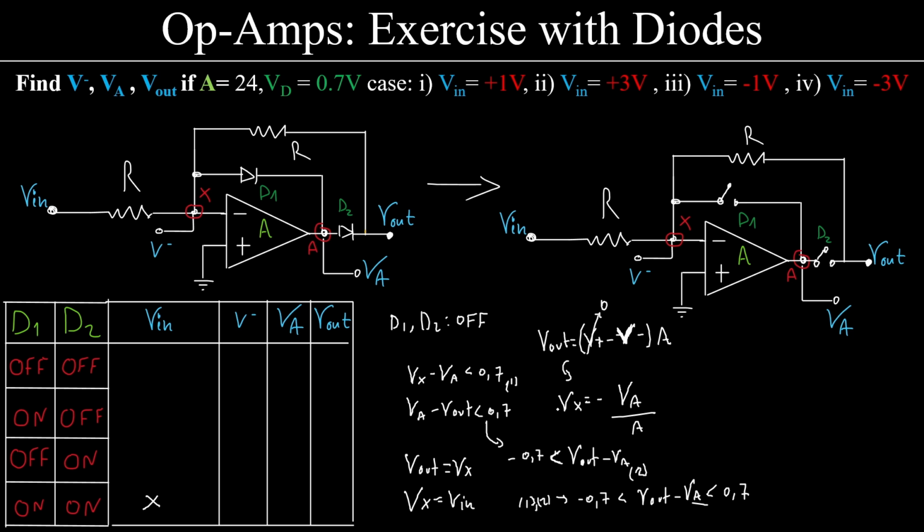But how about Va? Well, for Va, I also gained this condition over here. Va will be equal to -A times Vx. Therefore, this whole thing becomes the following. And now, if we do simple math, add these two, so it's 1 plus A times Vin, and then divide everything. 1 plus A is positive, so we won't change the inequalities, and we'll have eventually 0.028 with a minus.